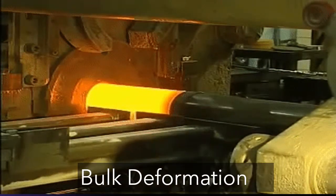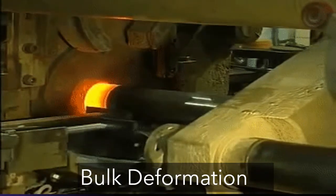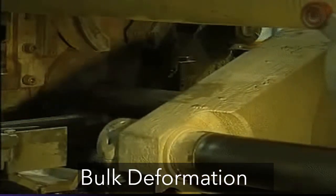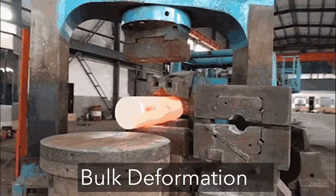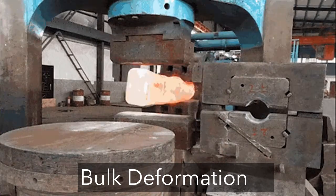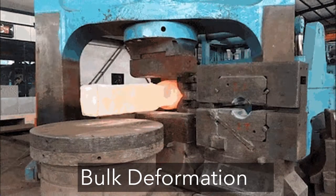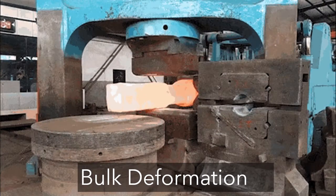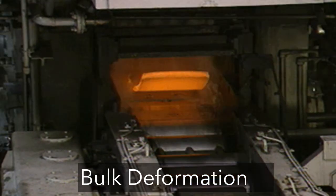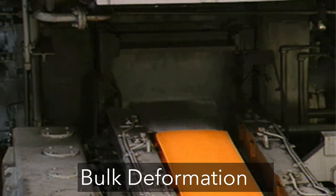Deformation processes are metal forming operations which cause a significant shape change by deforming metal parts whose initial form is bulk rather than sheet. Starting forms are cylindrical bars and pellets, rectangular pellets, slabs, and similar shapes. These processes stress the metal sufficiently to cause plastic flow into the desired shape. This can be performed as cold, warm, and hot working.